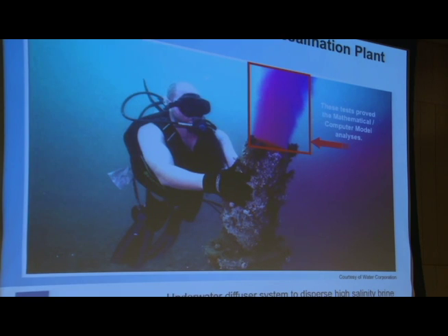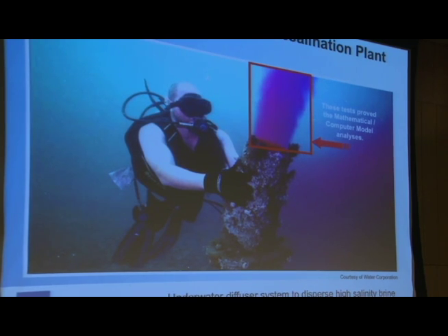It gains about 2 C going through the condensers, so it hits the plant at about 16 C. It then comes out of the plant having its salinity much higher and its temperature approximately the same, where it is then blended with about 100x the volume of condenser water and discharged to the same outlet the plant has been using for condenser water for some time. It relies on tidal mixing beyond that to diffuse and dilute.